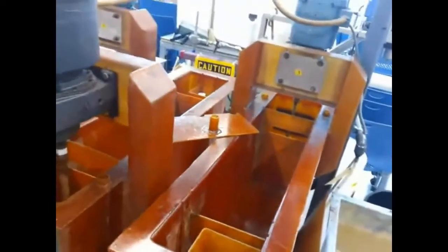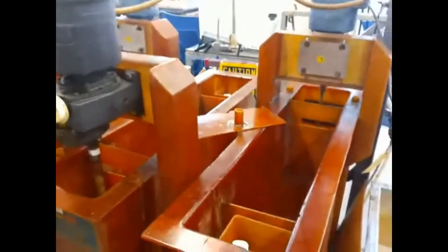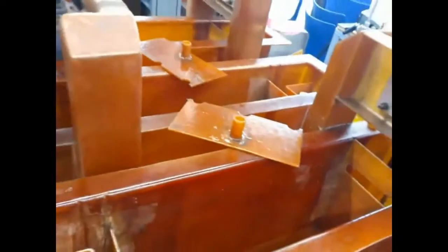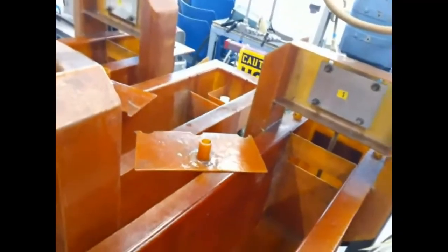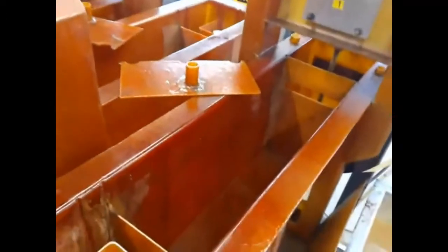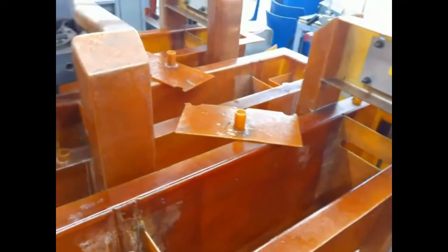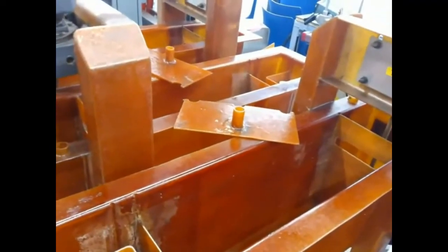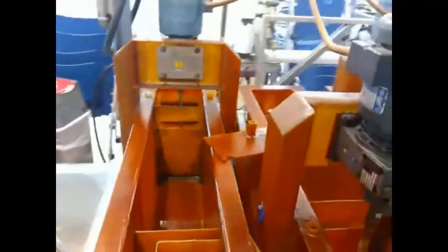That mixes the water and oil, and what happens is the vinegar likes to be in the water more than it likes to be in the oil. So it separates out, and then it goes into this settling tank here. And of course, as we know from salad dressings, the oil and the water separate because they're different densities. So you can get the separation of the oil and the water. The acetic acid goes into the water and gets removed from the oil. So the students do a set of experiments on this.